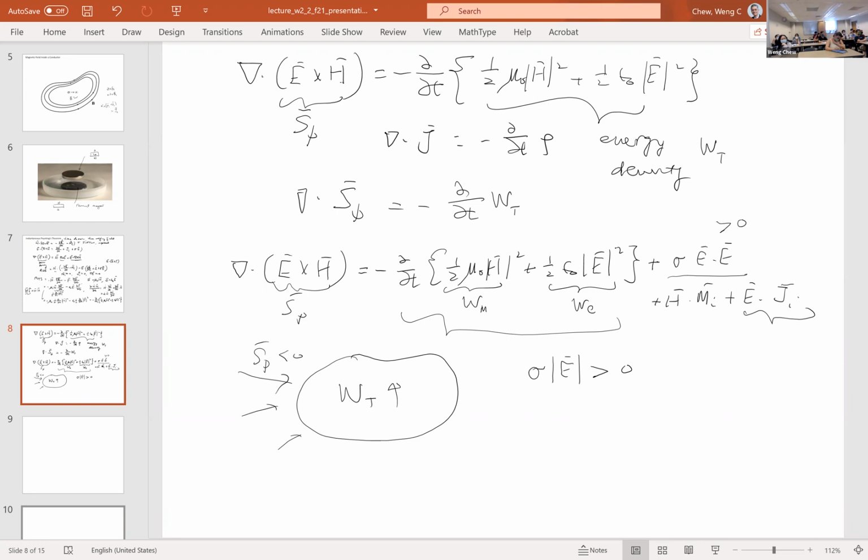It means that if you have a conductor, like a resistor, which we learned in electrical engineering, a resistor always dissipates energy. So if E dot J is positive, you are siphoning energy off from the system. If the electric field and the impressed current point in the same direction, that system is dissipative. That current source is actually not a source, it becomes a current sink.